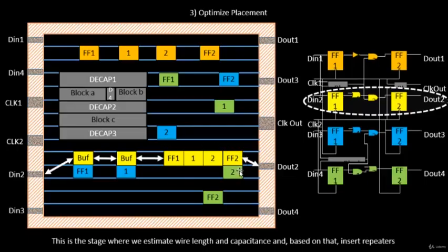Let's say this works at 2 gigahertz or something. In that case, we don't want to waste delays on the wires, and as a result of that, we have abutted these particular cells. So this is a very classic example of a high frequency circuit.